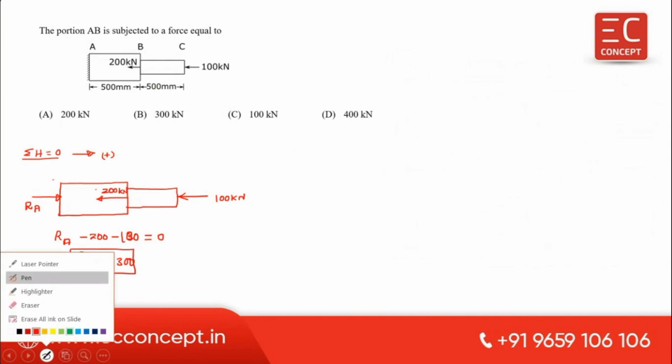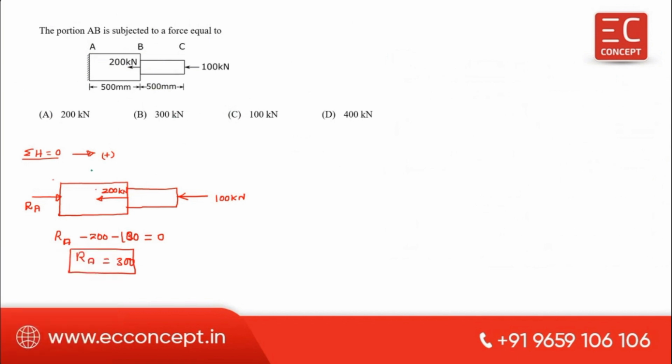If you want to calculate the force in portion AB, you have to cut a section approximately at the center so that we will not get confused. Cut a section at the center of this portion AB. This is A, this is B. Then you have to find the forces at this section from the left and from the right.